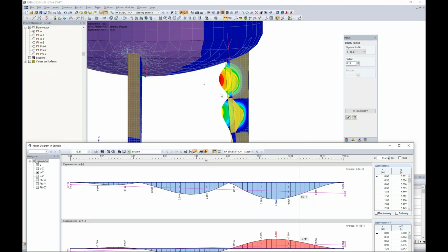This comes from the AISC Code of Standard Practice, and in particular, Section 7.13.1. It discusses misalignment of members and surfaces. These tolerances can be less than L over 500, where L is the distance between working points.